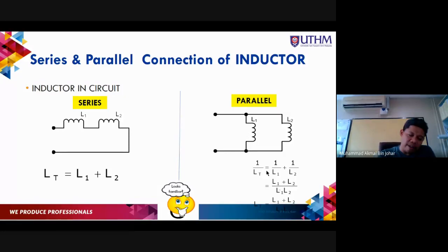In terms of technique, for series and parallel, resistor and inductor have the same way to calculate the total or equivalent resistance or inductance, while the capacitor has the opposite way in terms of calculating series and parallel. So it is much easier for you to memorize. Just remember that how to calculate resistor and inductor are the same.